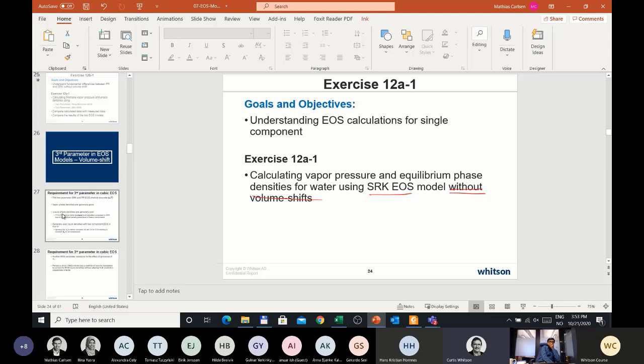So really, the petroleum engineering industry took the Peng-Robinson simply because the Katz-Firoozabadi paper was the first paper they saw. Keith Coats also, who did the 1980 paper on reservoir simulation, used the Peng-Robinson, and he was also a University of Michigan PhD student. So it was a little bit of an alma mater decision for the Peng-Robinson. Whereas for the SRK, it was the first thing available in commercial software in the early 1970s. So that's kind of the background for the two equations of state.